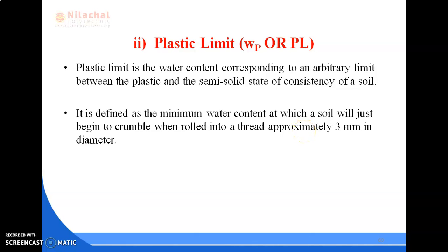So it is defined as the minimum water content at which a soil will just begin to crumble when rolled into a thread approximately 3 mm in diameter. So this is the actual definition of the plastic limit of the soil.